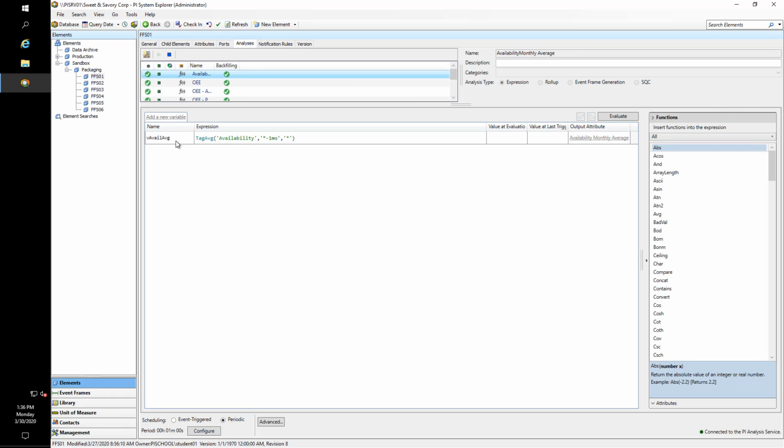it's actually relevant. Now, the reason these 1 minute evaluations are a problem is because they pose an unnecessary workload on the analysis service, especially when backfilling or recalculating the analysis over a period of time, like you may want to do with something like this. Let's say you want to do a backfill over the last 6 months, so you want to see what your last 6 months worth of information was. Doing that would mean running 259,200 evaluations. If instead we brought it down to daily and ran the calculation once a day, for example, we'd only have to do 180 evaluations for that exact same period.